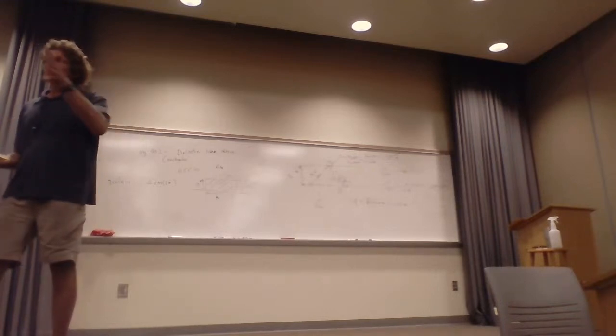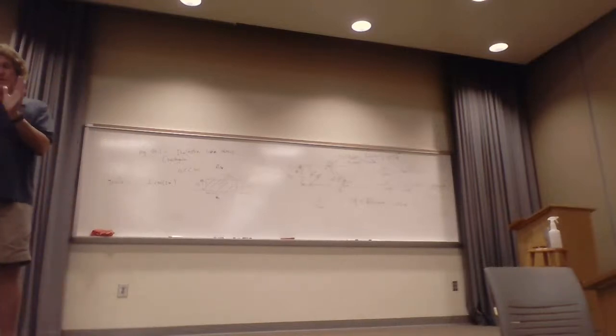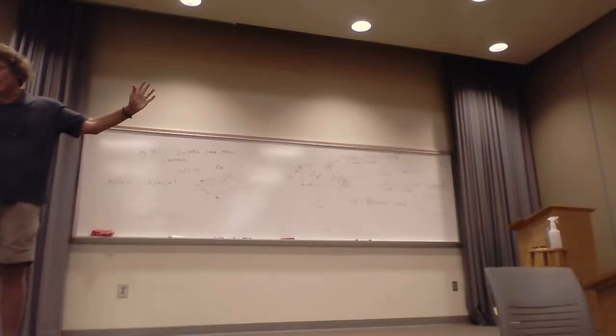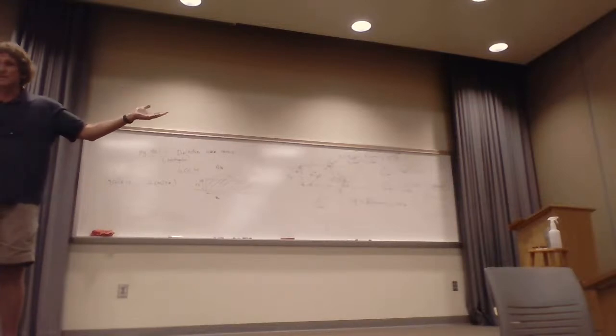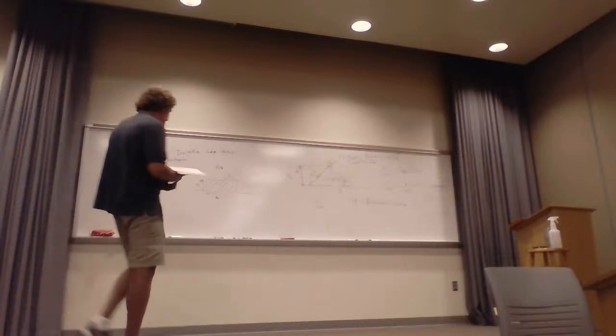But when those things are propagating down, if there are different speeds, when they assemble at the other end, there's no coherency. Then you get garbling, right? You may get roughly the same power down there, but it has no communication abilities at all, right? That's why you want only one mode. So that's what he does there with his equation.